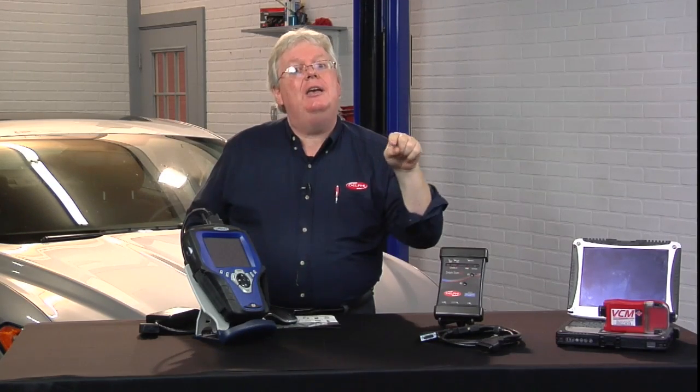Scan codes second if it's an electrical problem. I mean, the customer's complaining about a wobbling wheel. Obviously, you're going to set a rack and look at the chassis and steering suspension. But if you got an electrical issue, you got some kind of drivability problem, you got a warning light on, ABS even, go ahead and pull codes after verifying customer complaint. Pull the codes next. Then do visual inspection.